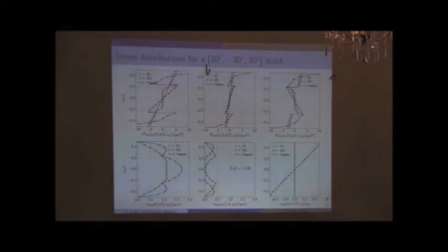So they are not exactly the same for the bending stress. And for the transverse shear stress, there is no Kirchhoff law of localization because it doesn't come out in Kirchhoff plate theory. So here you only see the comparison between the exact solution and the bending gradient solution. And of course there is no out of plane stress in the bending gradient theory, so both are zero, but I still plot the exact solution, which is not zero.